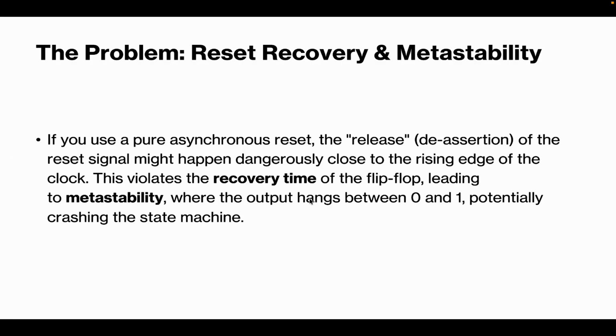This violates the recovery time of the flip-flop. It means it will enter a state where it is doing the operation but also doing the reset. It does not have the recovery time for the reset to be set to 0 so that it can perform the operation, leading to metastability.